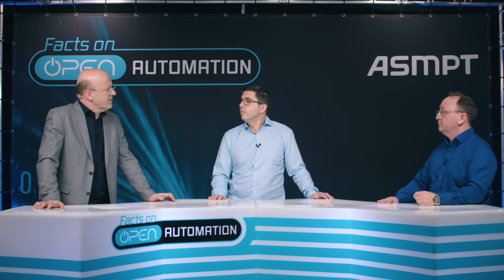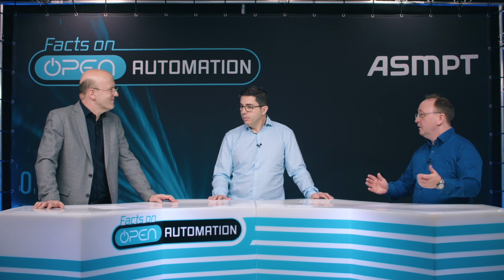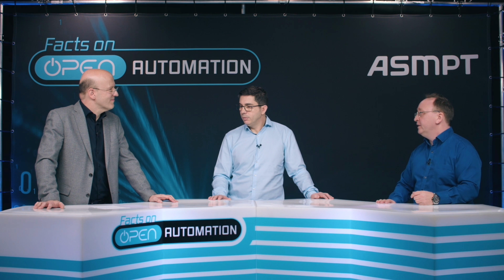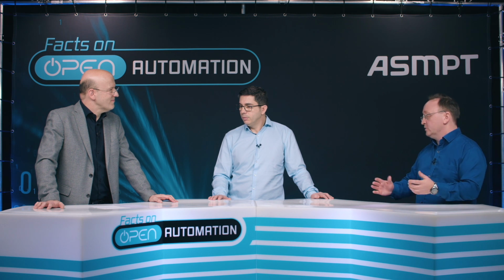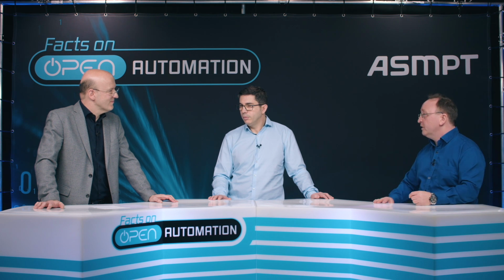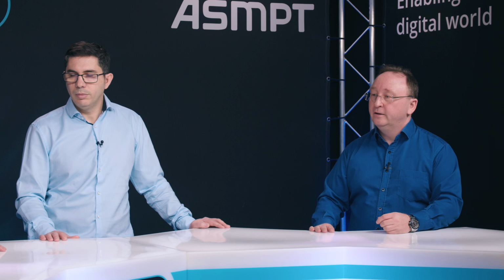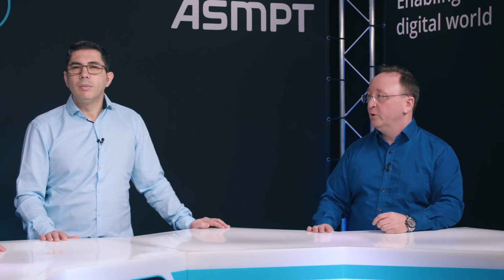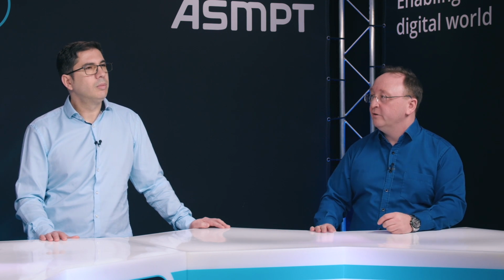I see. Wolfgang, we also add constantly new features to our machines. Can you explore on that? Yes, Laszlo. By our own, but also together with a lot of partners, we did include or integrate and also develop a lot of special feeding solutions. This starts with multi-stick feeders, 120 millimeter feeder, which is actually our own product, tray feeders, feeders for axial or radial type components, or even pin header cutting feeders.